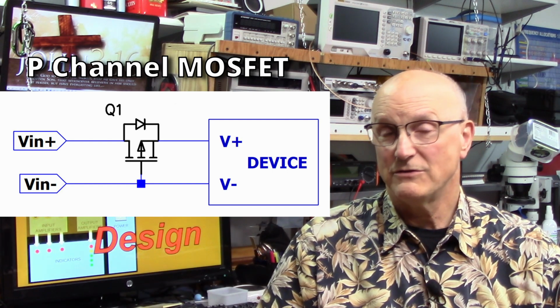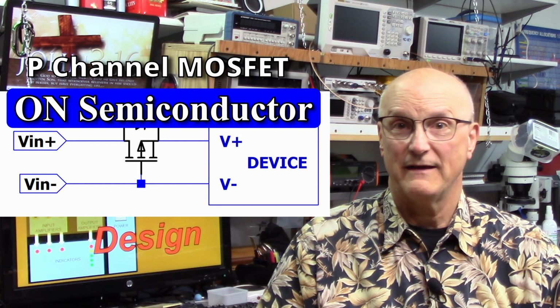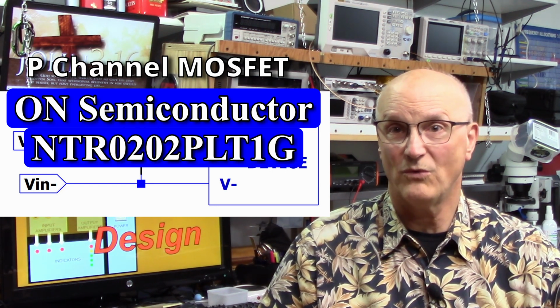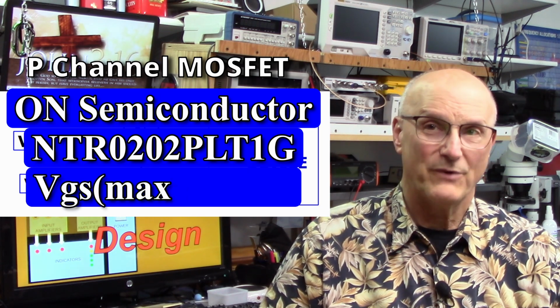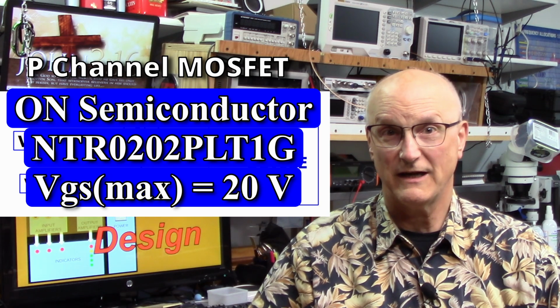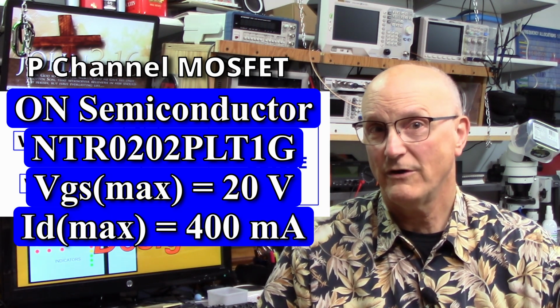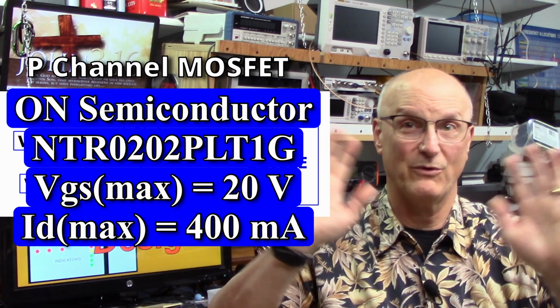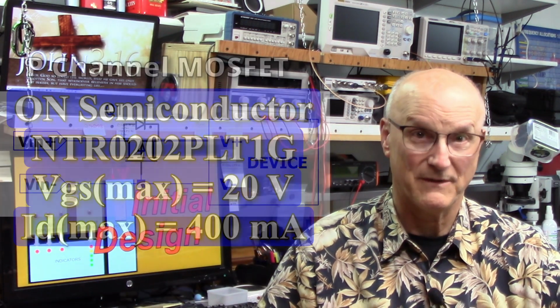Now, I'm going to use an ON Semiconductor NTR0202PLT1G. It's rated up to 20 volts gate voltage, good for this design, and 400 milliamps of continuous drain current. We're not going to be going anywhere near 400 milliamps.